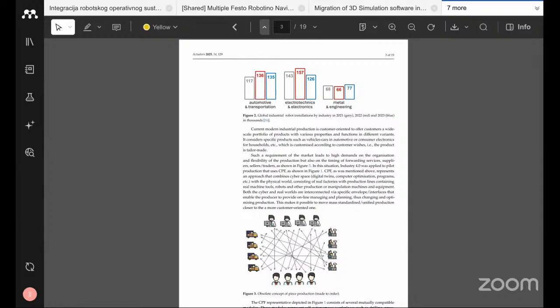Immediately, the PLC will send a message to the actuator. Then the actuator will move up and stop the box like that. It will activate the pneumatic press. The sensor will confirm that pressing is completed. The PLC will release the press. Again, the conveyor will start the operation.